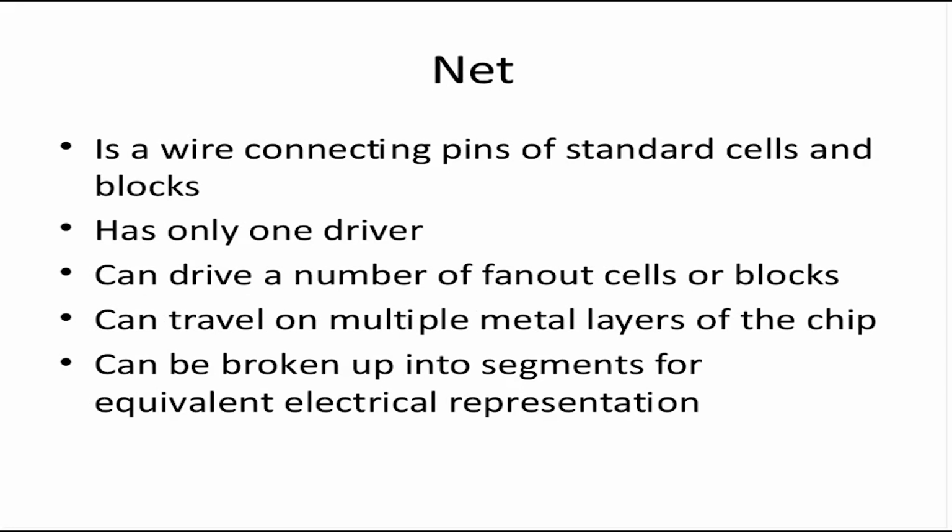The properties of a net are: a net is a wire connecting pins of standard cells and blocks. Any two cells would be connected by an interconnect or a net, and a net obviously has only one driver. There are nets that have multiple drivers, but in that case, consider a net that is being driven by two drivers.